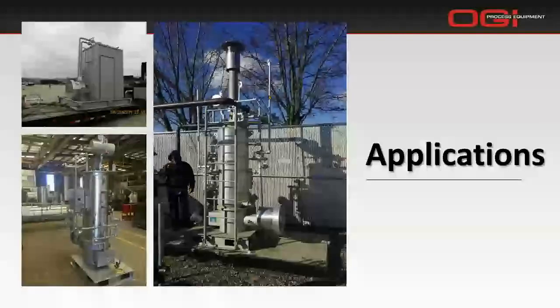And then I want to talk about a vertical bath heater. This is something that's been around, but it's been gaining popularity, and specifically where you may have a small station where you're fitting in a heater. So space constraint, as you can see, it's going to take about 1/3 of the footprint as opposed to a horizontal water bath heater.